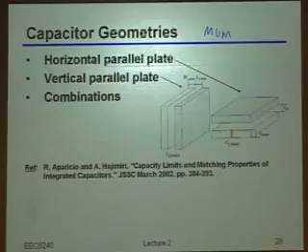The other way we can do it, which I believe Jethro suggested earlier, was we can flip this whole picture on its side, right? We can take some piece of metal, have it sit vertically like this, and then as close to it as we can, place another piece of metal that also sits vertically, and largely rely on the parallel plate capacitance between those two, okay? So, when I drew this picture, I was being a little bit, I shouldn't say fake, but the relative aspect ratios here maybe are not exactly correct.